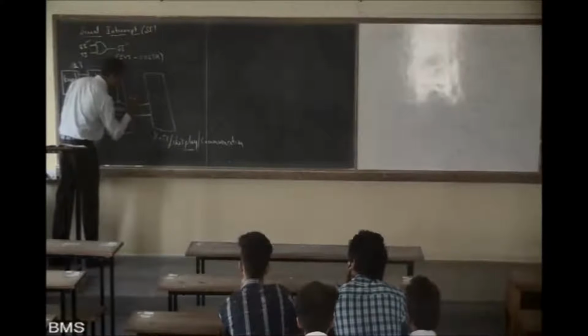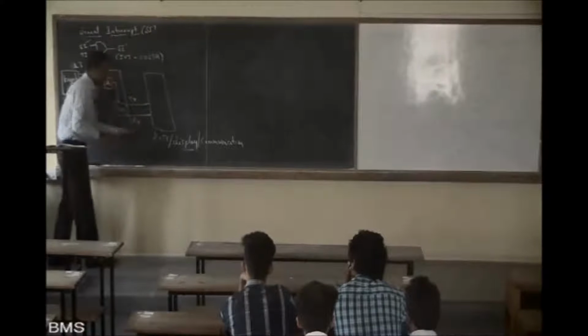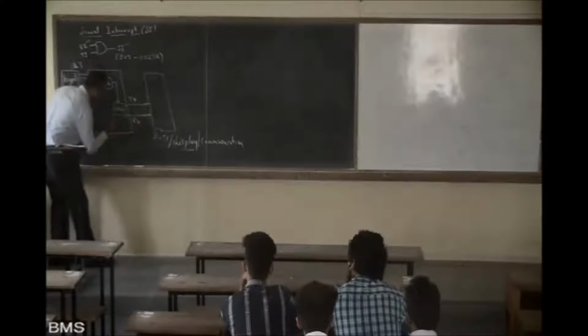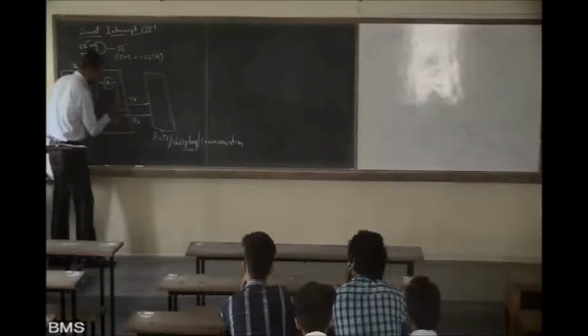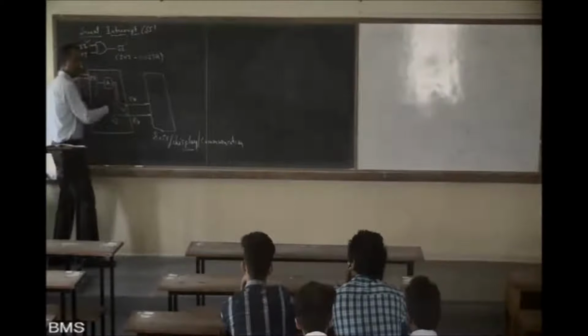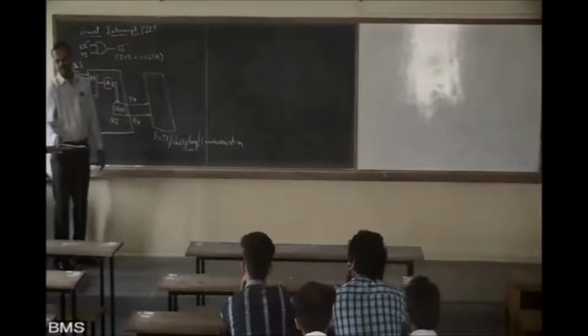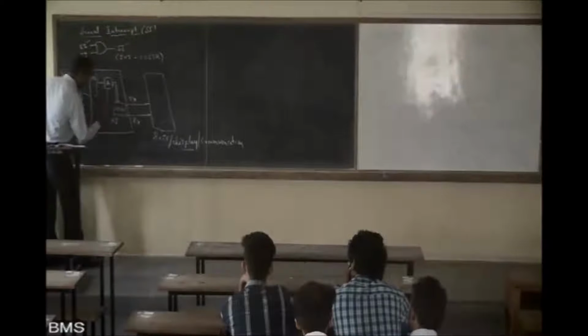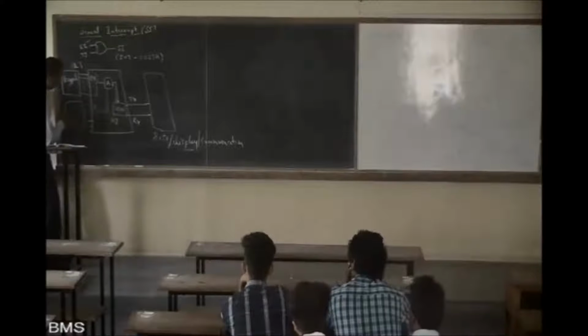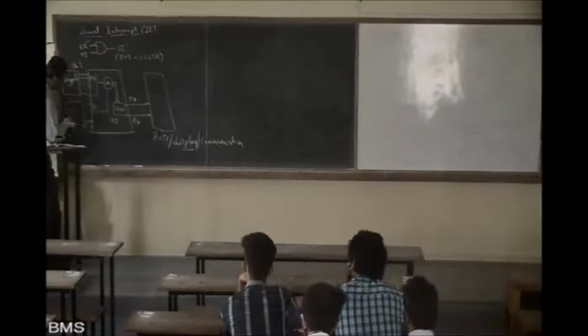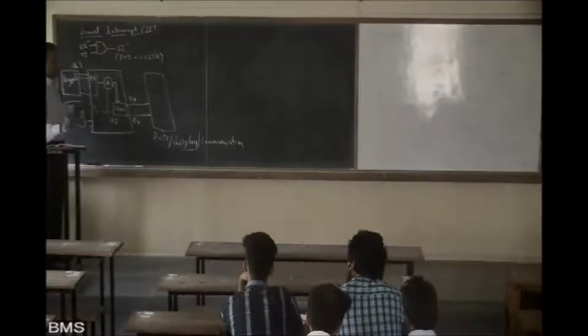This is TX, this is RX. When you receive the data, your RI flag will rise here. Whenever there is an RI flag, instead of putting a value from A to SBUF, you have to read from SBUF to A. Then send A to some other port, port 2. We'll say there is a display here. Getting what I'm saying? This is a program that we should write.